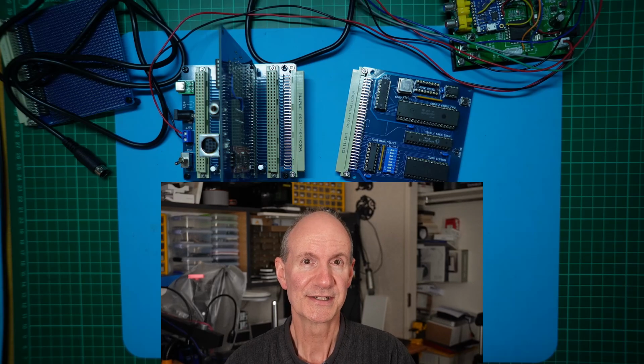A divide by 1 option is also available, but this requires the clock transitions to be synchronized with the data stream, whereas for the divide by 16 or divide by 64 options, the MC6850 does feature internal clock synchronization to the data stream. Therefore, the divide by 1 option is really only useful in an application where you are receiving a data stream that includes a synchronized clock signal.